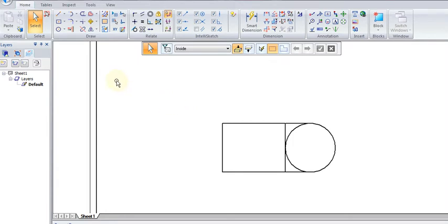Now what we want to do is we want to use the fillet tool and the chamfer tool. Now a fillet is simply a bevel or a rounding of an edge, and a chamfer is also a bevel, but rather than being round, the chamfer is a flattened edge. To use either of these tools, we go to the fillet tool, which is in the draw container, and we'll start by using a fillet. So we'll just click on the default tool. To use the fillet, essentially what we do is we click on any two edges that we want the fillet to be at, or to be between.